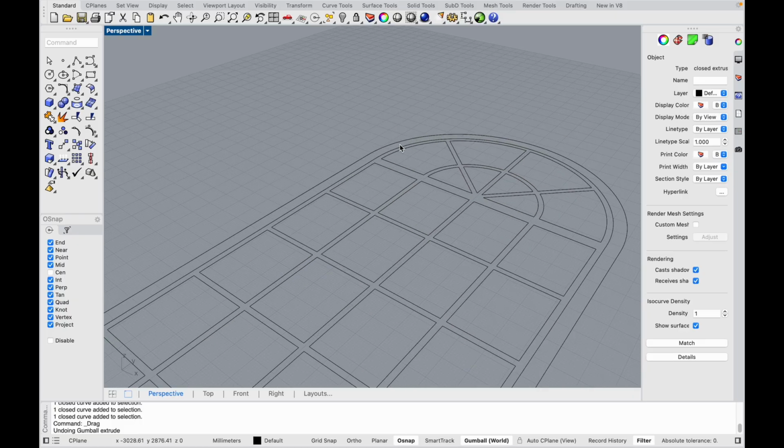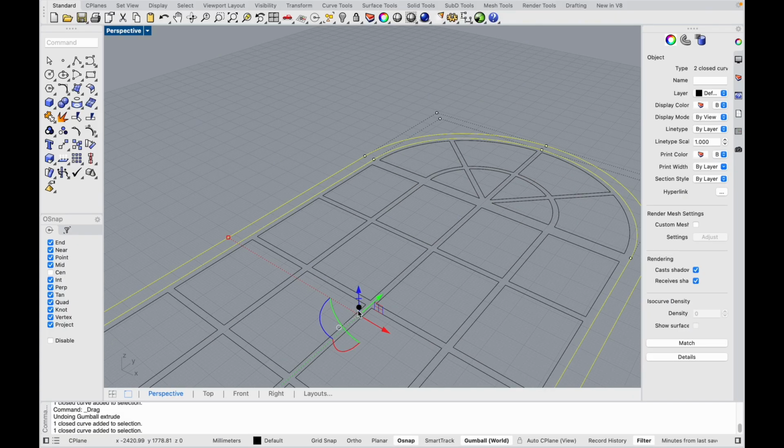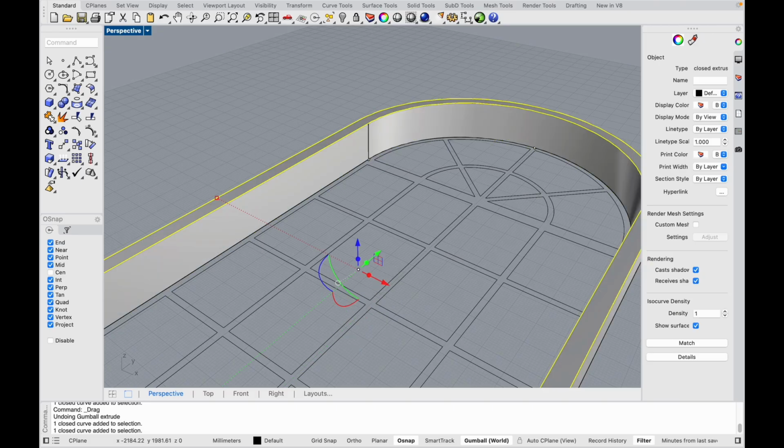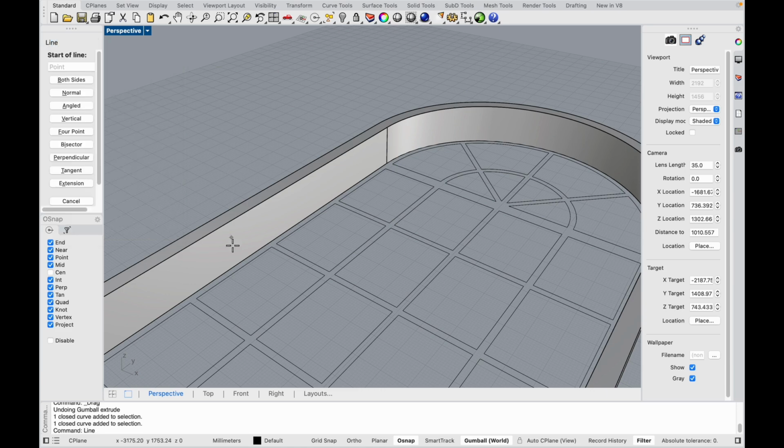But if you select the curves and click, not click and hold, but just click, you can type in the distance. And let's say that the extrusion of our frame will be, for example, 200, because in this direction the frames are always bigger. So let's just draw.